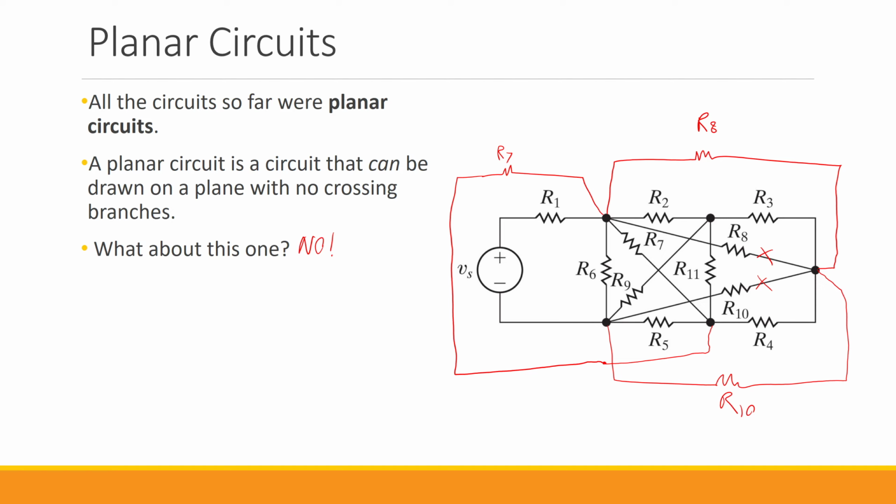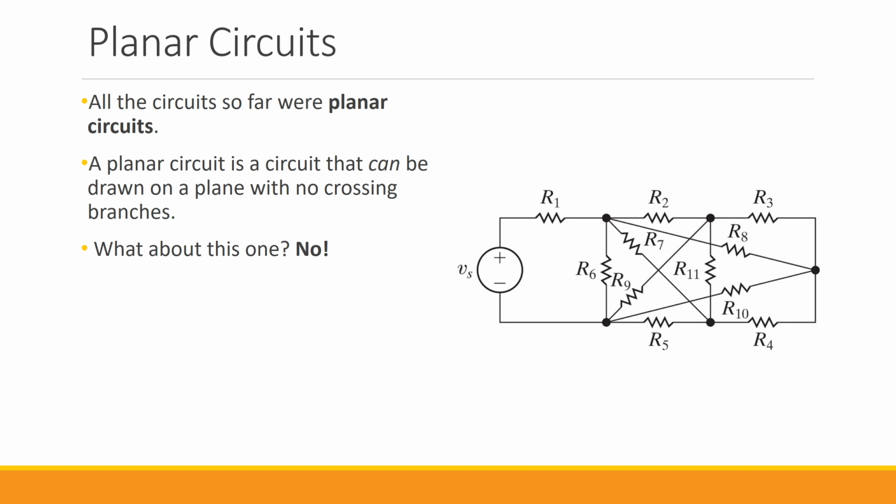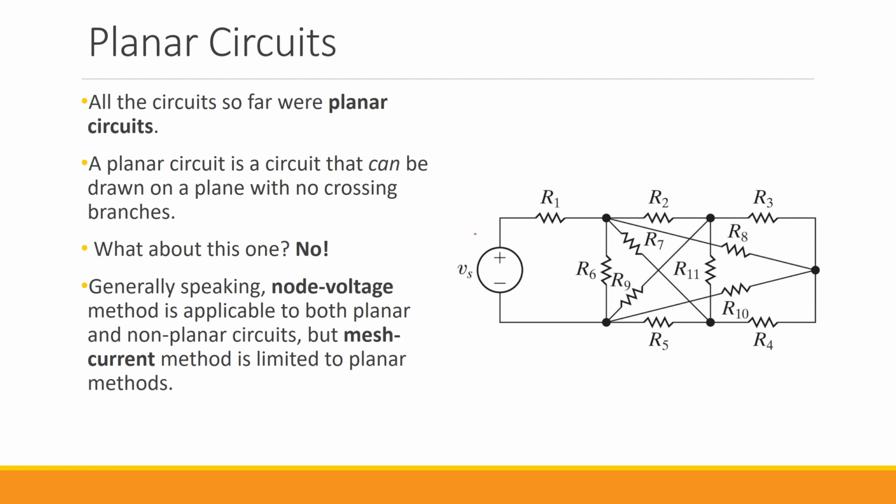So this is a very useful concept that I wanted to introduce here, because I am going to move forward with more advanced techniques for analyzing electric circuits. Namely, in the next lectures, I am going to introduce the node voltage and the mesh current techniques. Generally speaking, the node voltage method is applicable to both planar and non-planar circuits, but the mesh current method is limited only to planar circuits. So I will go over more details of these two techniques in later lectures.